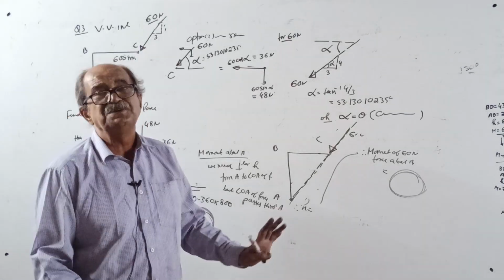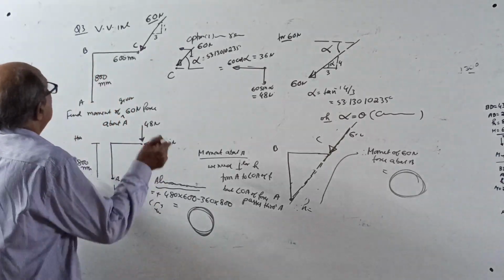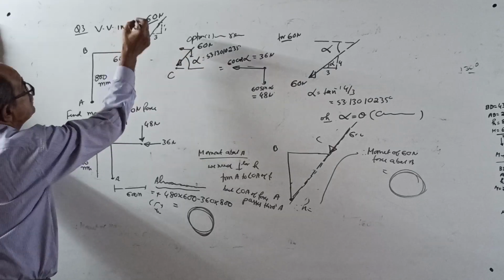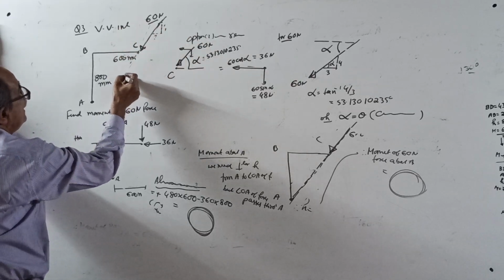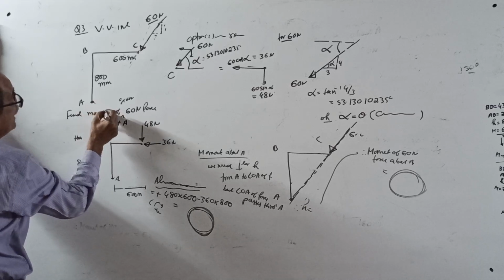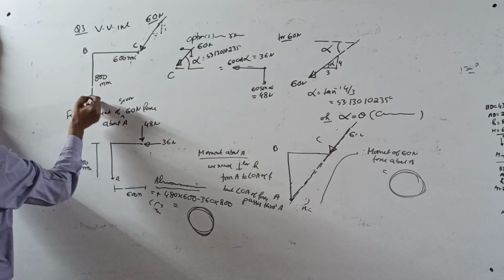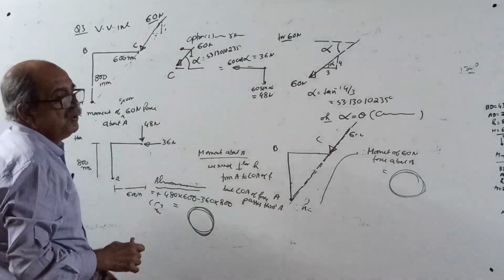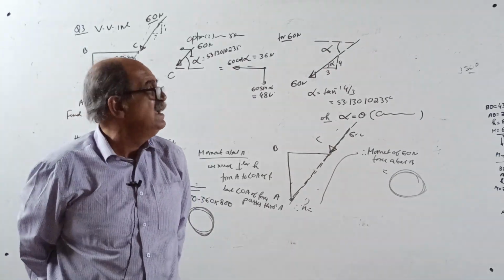This is a bonus question. Make a note. If the point lies anywhere on the line of action of the force, the moment is zero. In the first question, the force was steep, with a perpendicular. In the second question, it cut somewhere here, and a perpendicular was there. In this question, it passes correctly through A. Therefore, the moment came 0. Today's class is only for understanding.